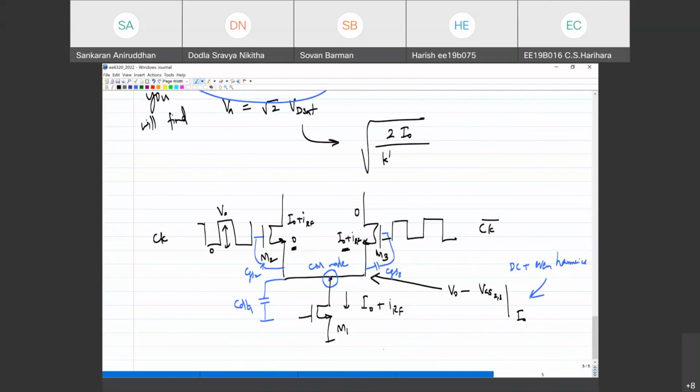You'll get a DC voltage, on top of which every time it switches, so every half period T, that will happen twice a cycle, you will get a glitch there. So you may see something like this. Actually, you will see something the other way. I mean, you may see something like this.